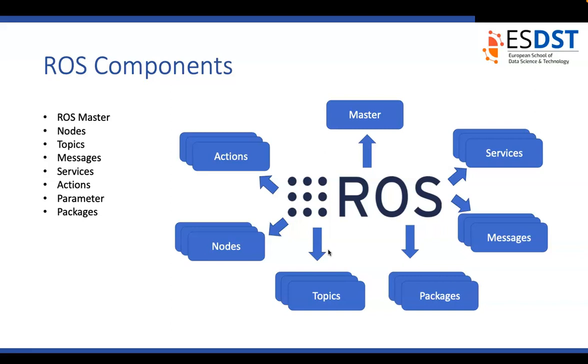So what we can do is subscribe to these topics and get all the information. If you want to subscribe to robot A velocity, you can, and similarly robot B velocity, and then we get information on these two robots through these topics. So information is published on the topics, and then you subscribe to it.